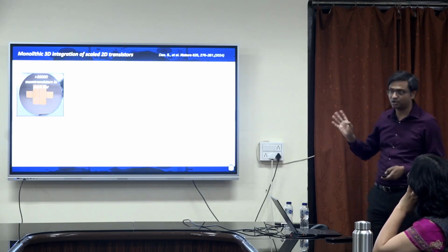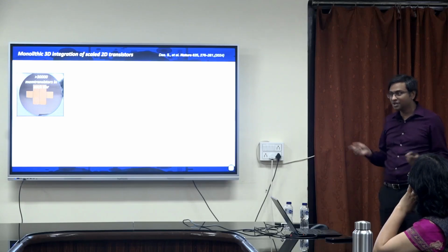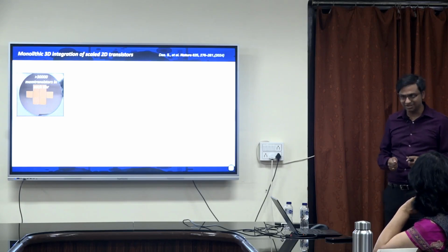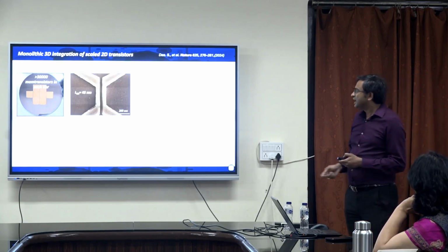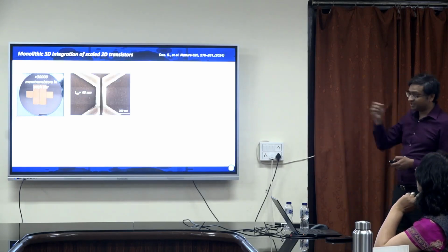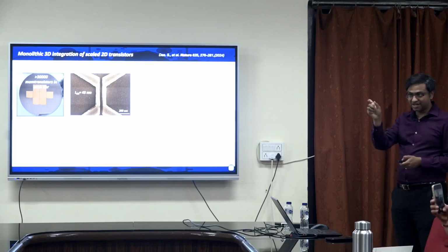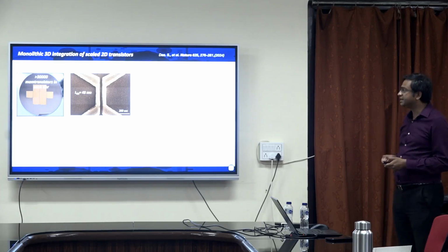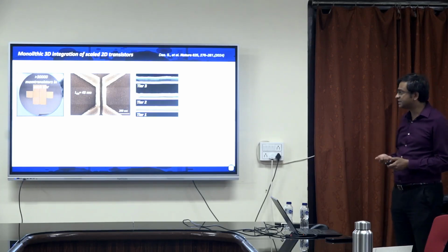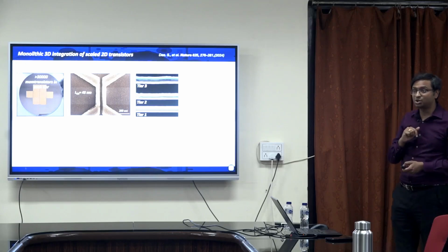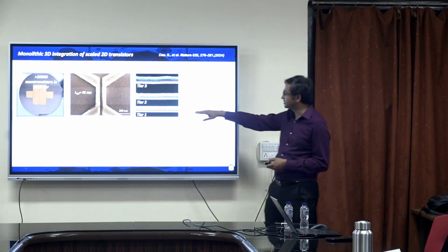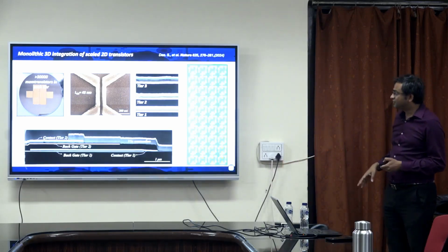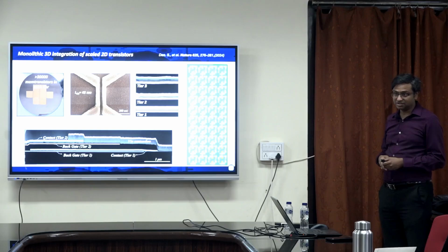We could do it because we have automated measurement capabilities as well. It's not like a student is going and measuring 10,000 devices, which would probably take their entire PhD. We can make these devices pretty small, 45 nanometer channel length. I have also shown you channels even smaller. We can go down to 20 nanometer channel length, extremely scaled devices, which means that this technology can be scalable. And as I told you, we don't stop at 2 layers. We have 3 tiers of devices, 1, 2, and 3, and therefore you can now start making all these vertical circuits.